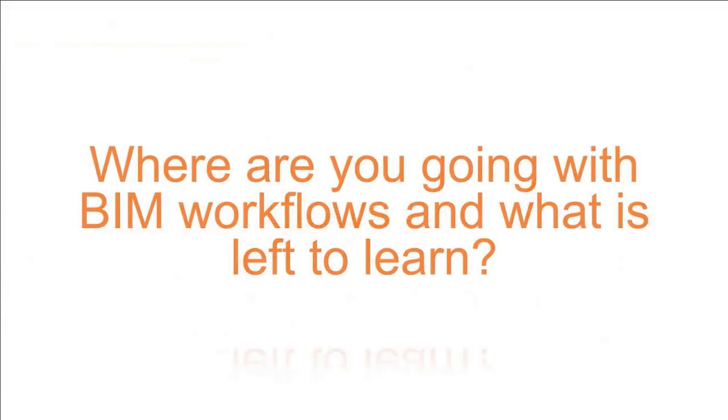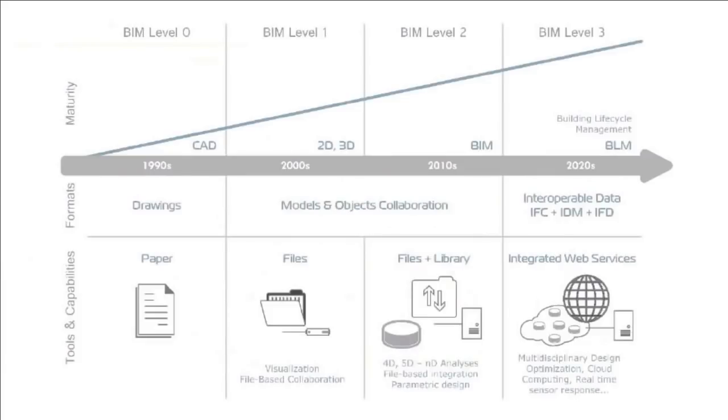And I'll jump in on that too, the BIM capability of Vectorworks. One of the big things with Vectorworks, Renee, is that you can literally assign any kind of data to anything. Now, Vectorworks comes out of the box with certain things that already have the ability, or they're called plug-in objects, that already have data attached to them. So, for example, in Vectorworks, there's plants. Plants have a database that's attached to them, so you can assign a specific, in AutoCAD speak, it would be a block. In Vectorworks speak, it's a symbol.